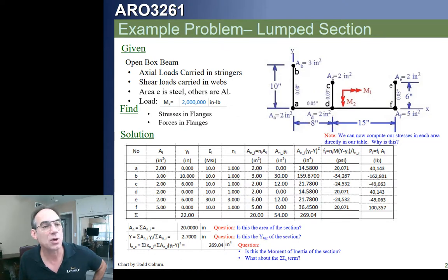Now that the stress is correct, to calculate the force, you're multiplying by the area, not the inertia. That's giving you the total force on that piece. So you'll notice the steel piece, 24,000 psi, multiplied by the area, 2, gives 49,000 pounds. It's not times the n, not times the inertia, okay?